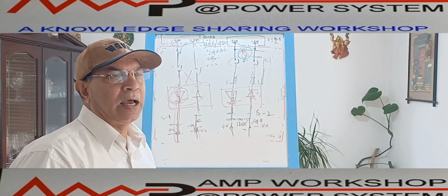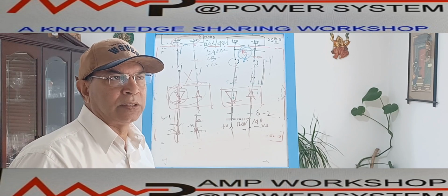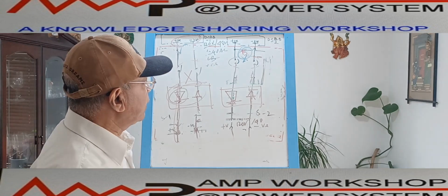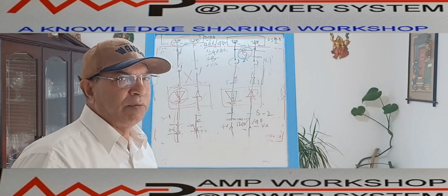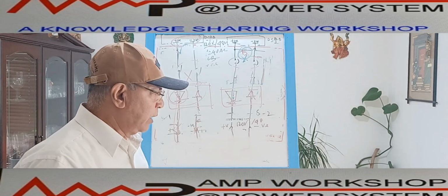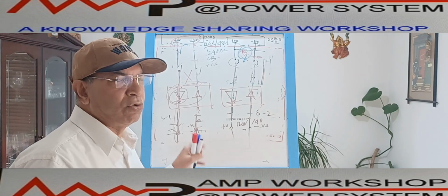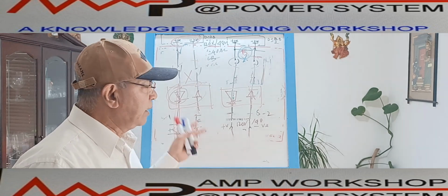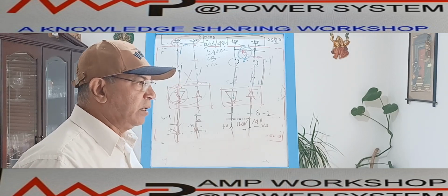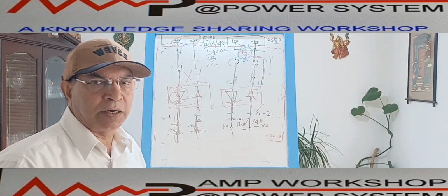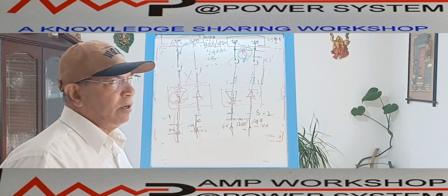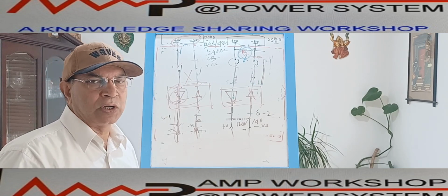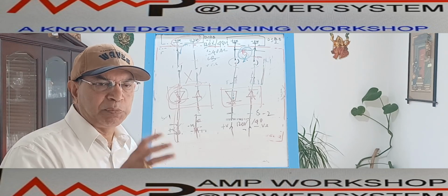Okay, and I have already discussed this. In addition, there is another point I want to highlight in the switchgear drawing. We have discussed the various switchgear control schematics and the power changeover scheme, everything. But when you receive a drawing from the switchgear vendor, generally for medium voltage and high voltage switchgear, they give a separate drawing for each panel.